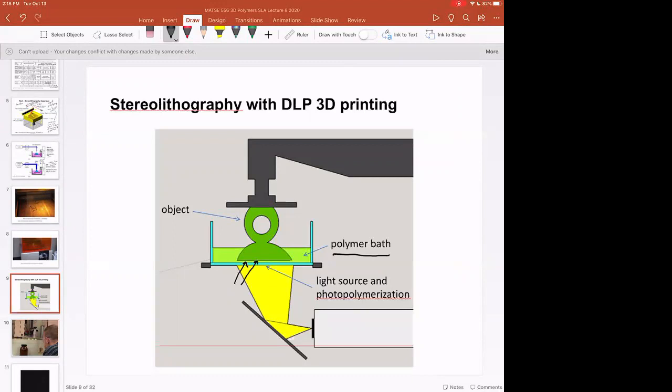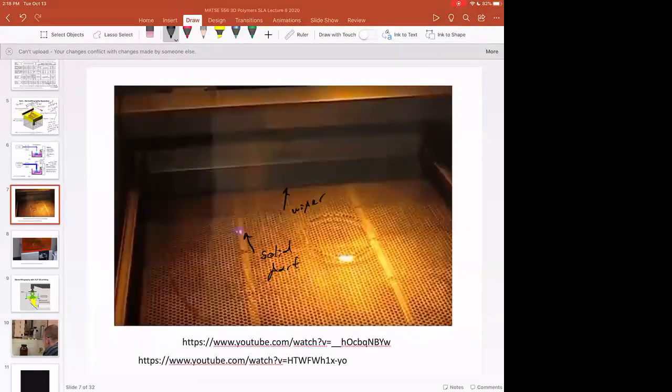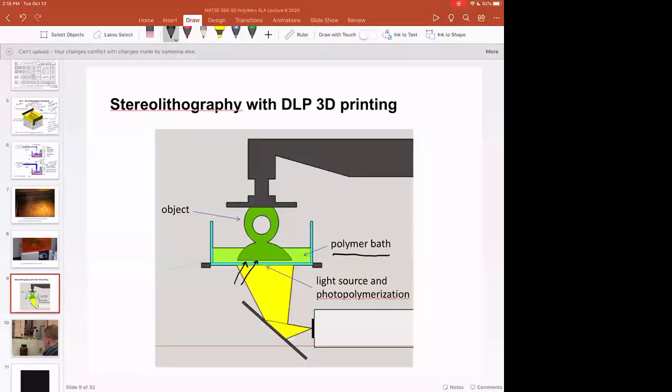And so as long as the viscosity and surface tension don't change, the resolution of this process is exactly the same as the resolution of this process. It's just if you start to get old resin or if you start to get aging of the resin as you're building, that can cause problems in both of these. Even we could talk about getting bad filling in here.